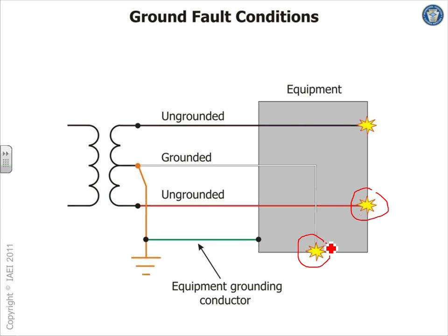What happens if you do that? A neutral to the ground. If that happens, nothing is going to trip, except now this guy will be carrying current as well as the neutral back, right? So you go open the green conductor to work on it, you get zapped, because it's carrying the unbalance between all these fixtures in this room.